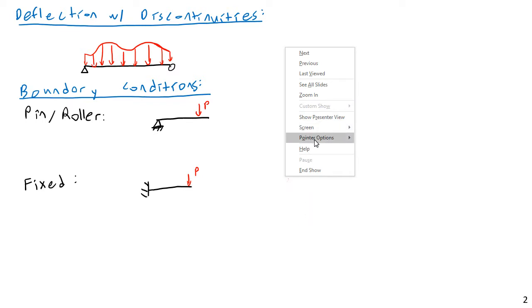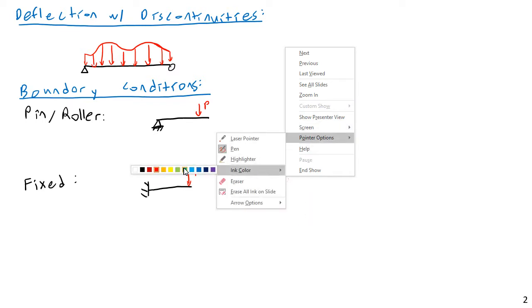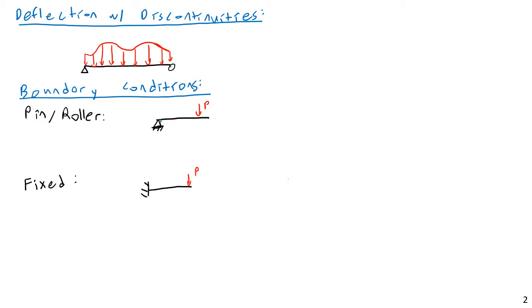So when I do this, what happens to the shape of each? Well, a pin joint, of course, is unable to resist rotation, so it's just going to bend downward like this. The end is actually going to rotate. The fixed support, however, is going to be able to resist rotation, so its deflected shape is going to look something kind of like this, or maybe more like this. Initially it's joined up very firmly with the support. It's not rotating at all. But then it starts to droop down as it gets closer to the applied load.